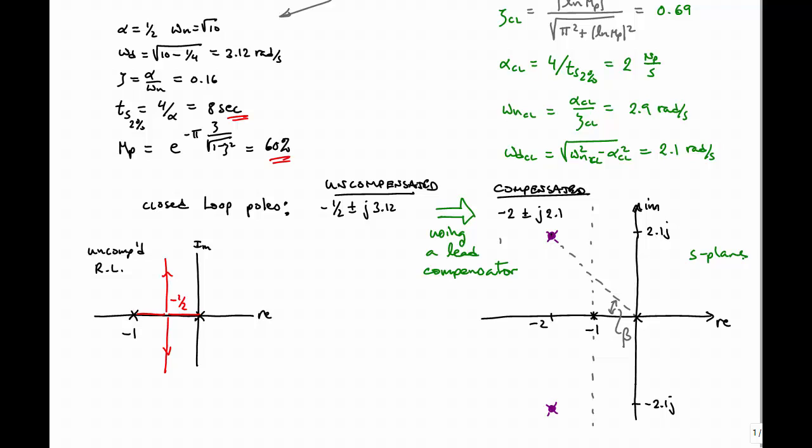Well, you don't need to add or subtract an angle contribution from this desired closed loop pole, because this is not an open loop pole. This is the closed loop pole. This is a point on the root locus. And so I draw it differently, more as a solid dot and then a kind of an X through that. So hopefully that will be helpful to you, as it has been helpful to me.